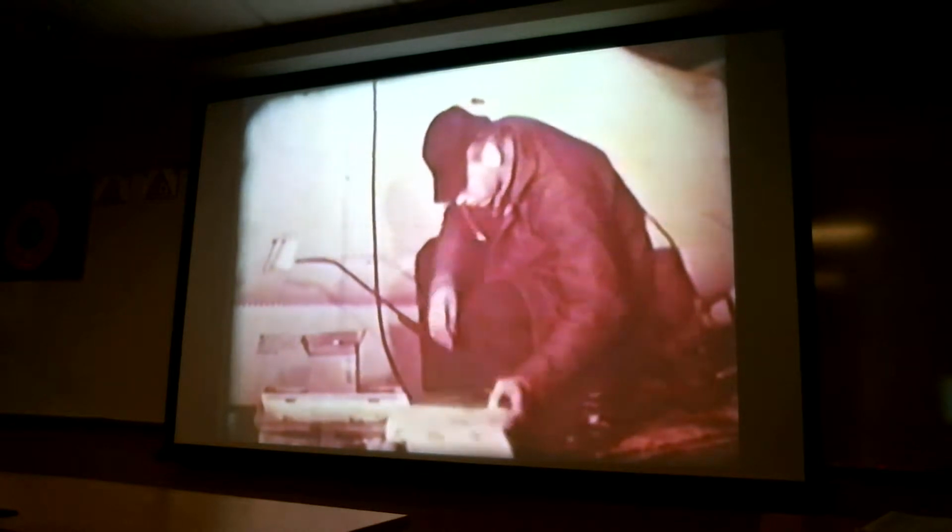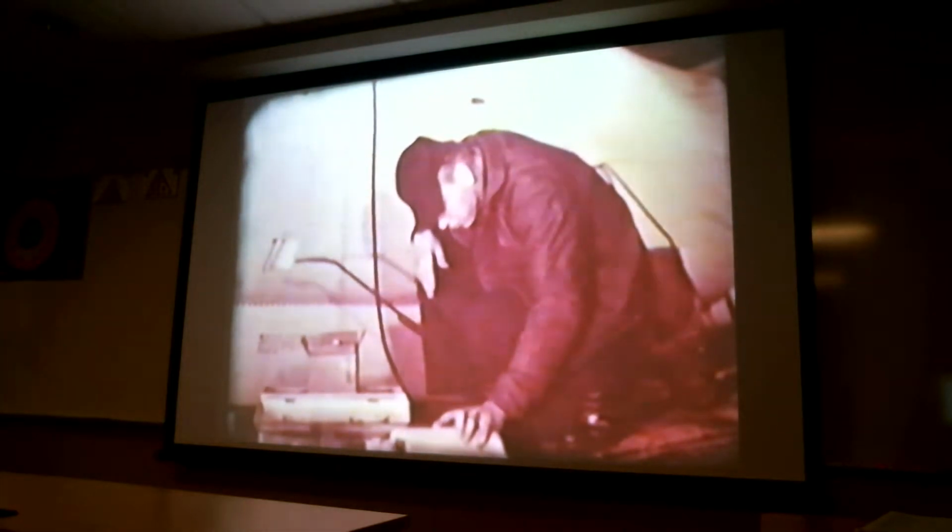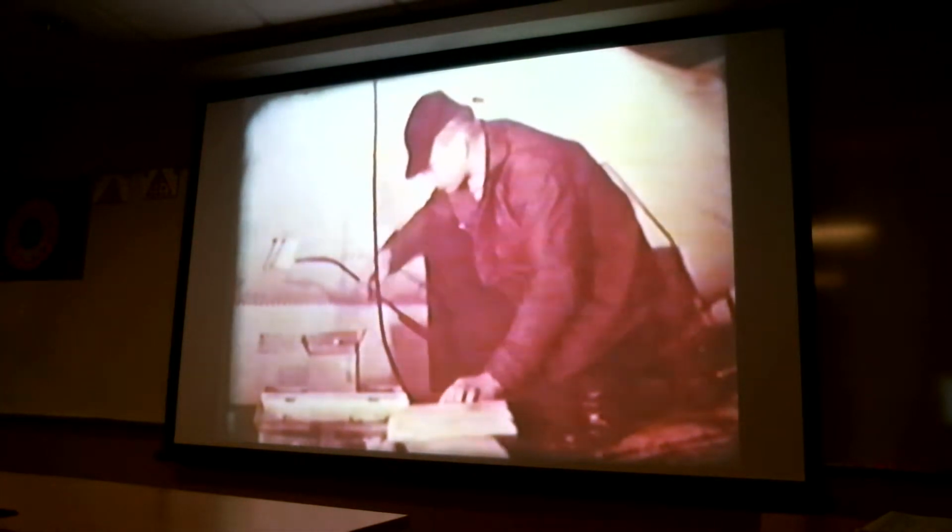Whenever you must replace a component, refer to the procedures outlined in your handbook of maintenance instructions. Experience has proven that the fastest way to get a job done is to go by the book, step by step. Even though you may have replaced hydraulic components time and again, take time out to refresh yourself. It will save time and material in the long run.